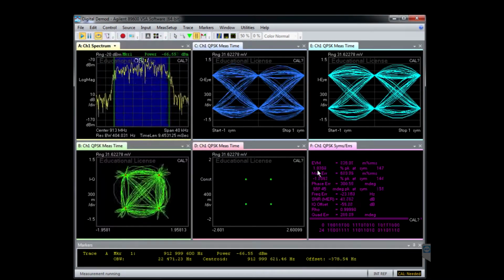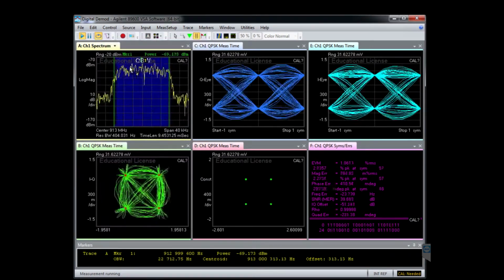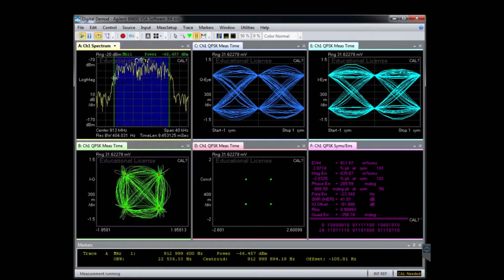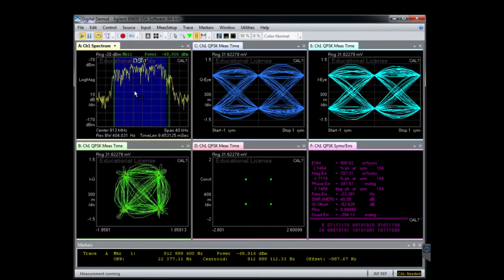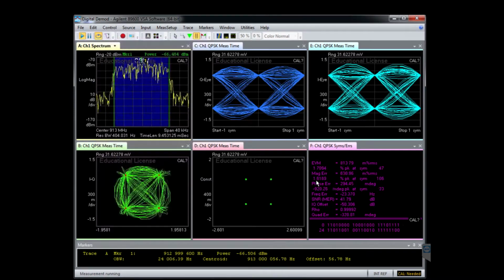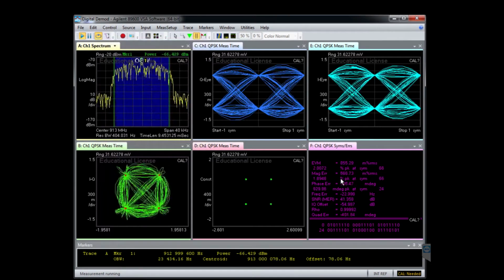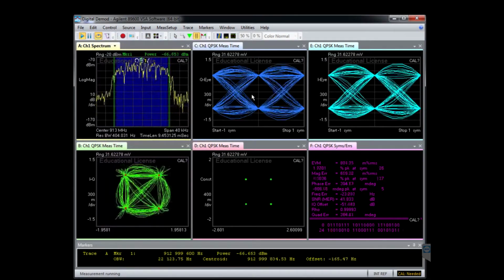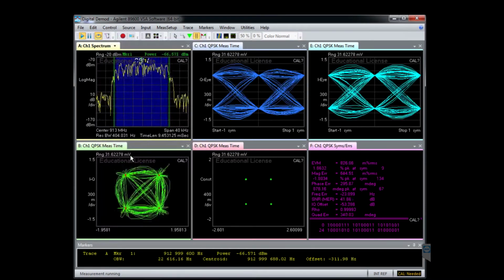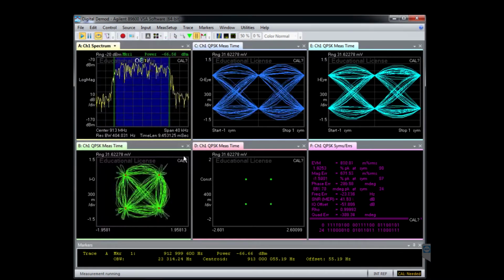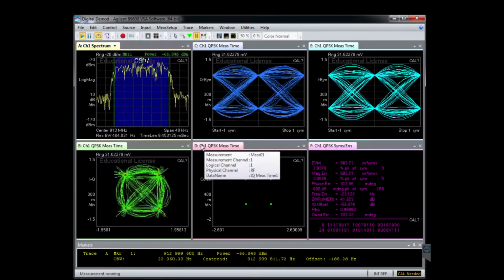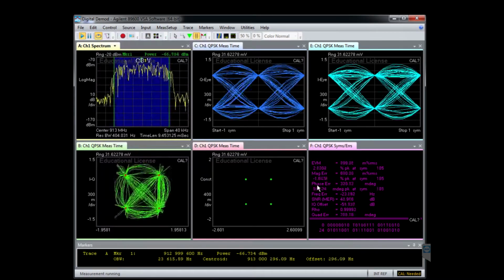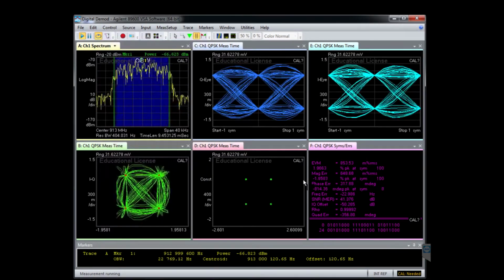You can take the SNR value that you have estimated in the previous part of this section to estimate the EVM, and the value that you get, you can compare with the statistics provided on this last plot here. So you can take a snapshot of all these measurements for each transmission power, and when you do your calculations of SNR and EVM, try to compare them with this and provide your comments.